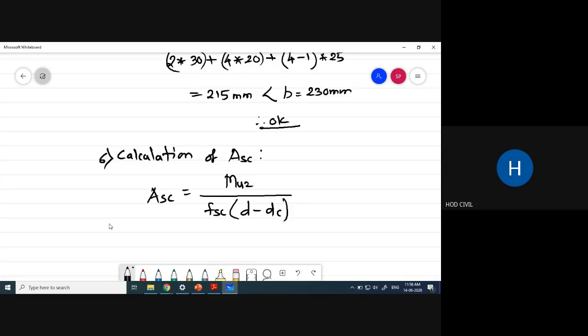We use all the relations related with the stress strain curve. Now when we go for Fe415 grade steel, the calculation for FSC is not so straightforward because the stress strain curve is not linear, and we have to make use of the larger table which we have prepared. I will go back to the slides now.